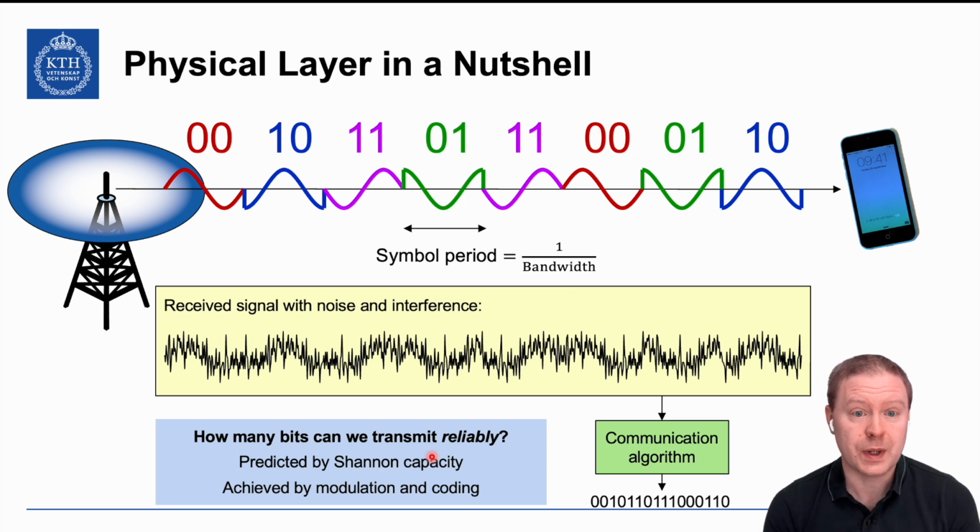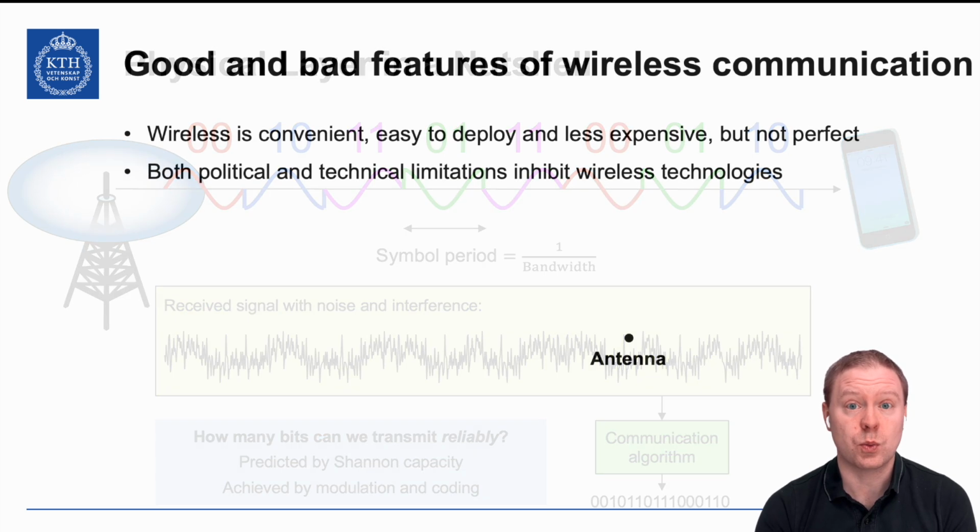And we can compute a particular value based particularly on the signal to interference and noise ratio that we are operating over. That tells you how many zeros and ones that we can be delivering. And then there are modulation and coding schemes that are actually doing this mapping here between a sequence of zeros and ones, which doesn't even need to be an integer number, and the number of different segments that we're transmitting of different shape. So this is the basic of our physical transmissions in wireless.